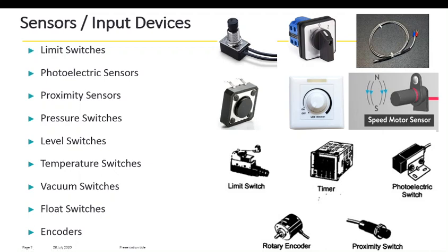Whenever we press this selector switch, the speed of your fan will increase or decrease, as we are able to select various steps by using various resistance arrangements, changing the output voltage.